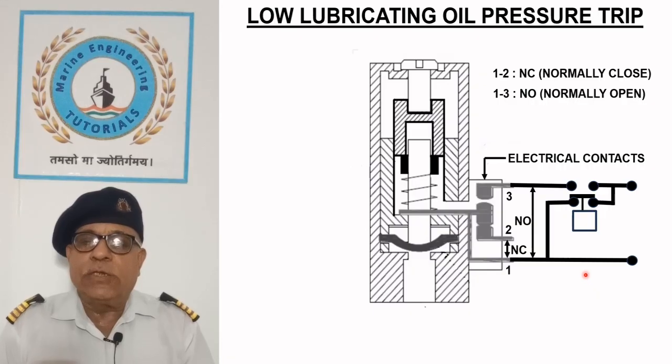Pressure switch is equipped with two sets of contacts, normally closed between 1 and 2 or normally open between 1 and 3. These pressure switches may be used for different purposes. Normally open contact is used for low lubricating oil pressure trip as shown in the sketch.